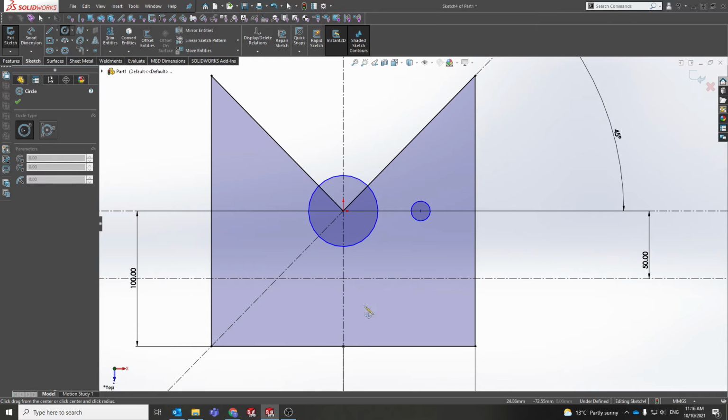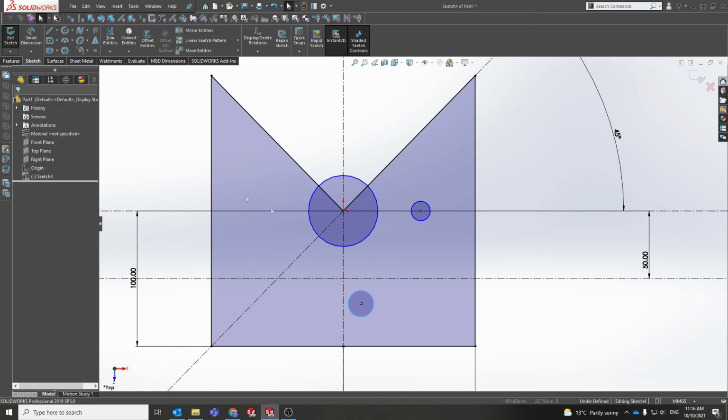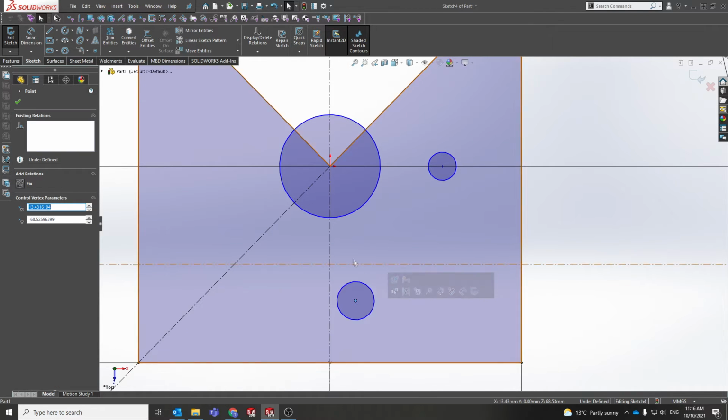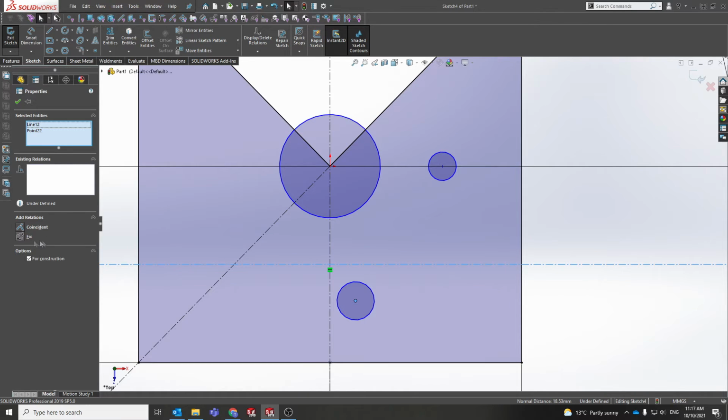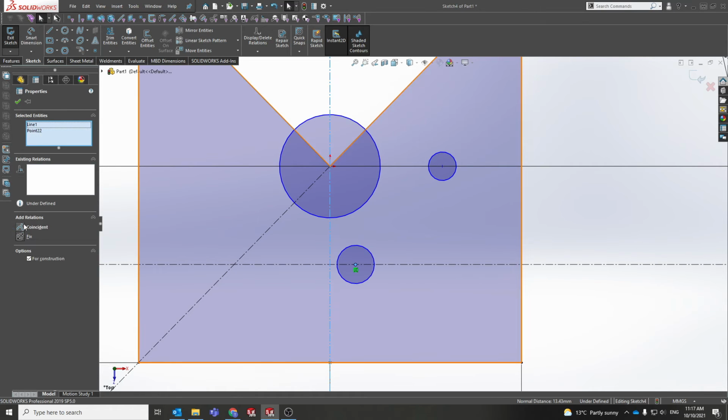So there's two things you can do here. You can either draw it somewhere else and go, okay, I'll draw it over here then, and then what I do is I click this point here. I'm going to hold Control, select this line here, and now I can add relationships. So I can go, okay, I want to constrain it to you. I'm going to click off, click again, holding Control, click this line, constrain, coincident, sorry, and now it is locked to that point.